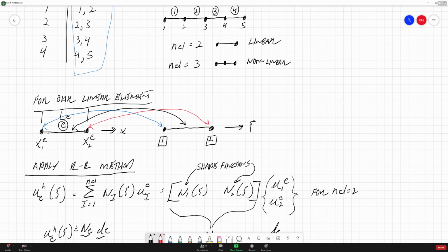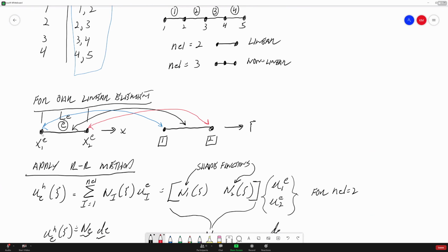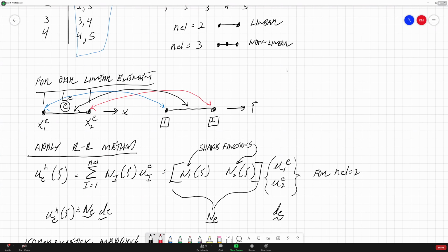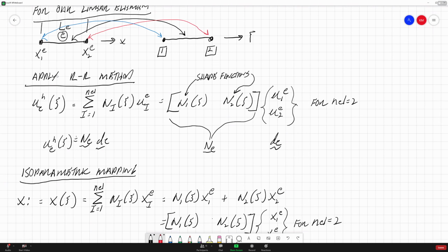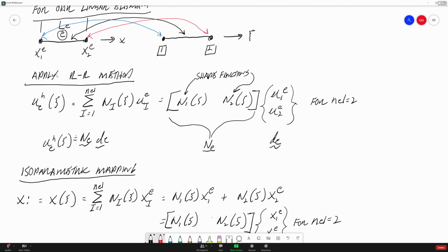And oh, by the way, I have to do this mapping to go from a global coordinate system for our part to a local coordinate system in this C space. So we're doing that. And then there's this other method called the Rayleigh-Ritz method where we're going to introduce these shape functions. And the shape functions, remember, at the node, the shape function is 1, and at the neighboring node, it has to be 0. So it goes from 1 to 0.